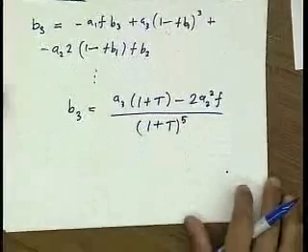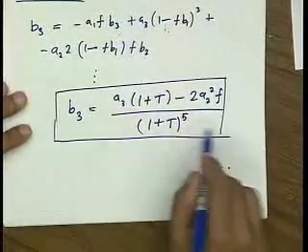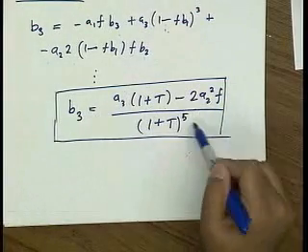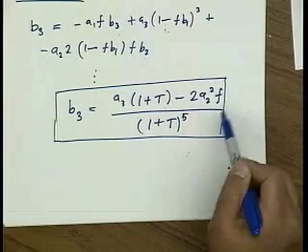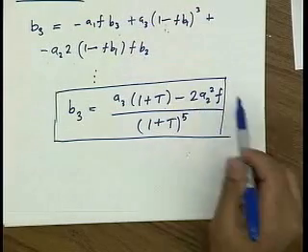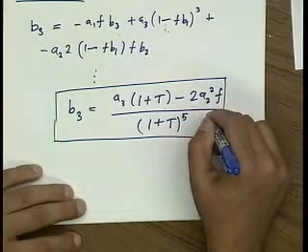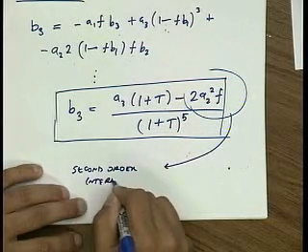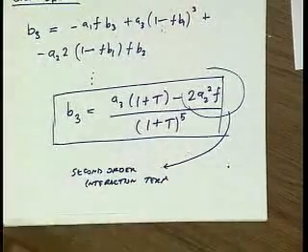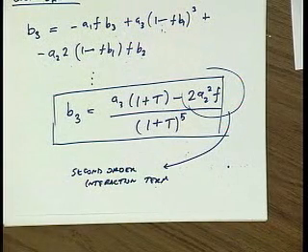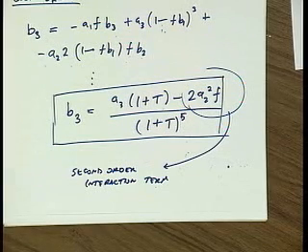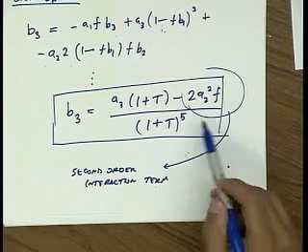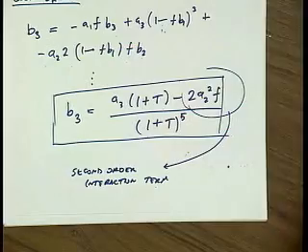Okay, so there's some good news and there's a little bit of bad news. The good news is that compared to A3, we can see that by 1 plus loop gain to the 4th power, we get a reduction. The bad news is this term, because this term actually introduces cubic order distortion in a system where you didn't even have it to begin with. This is called the second order interaction term. Remember last lecture we talked about a FET, and we said ideally a long channel FET has no cubic. But if there's any kind of feedback in that FET, for instance, source resistance, shunt feedback through that Miller capacitor, if there's any kind of feedback, which in reality there's going to be, then second order interaction will generate cubic distortion.